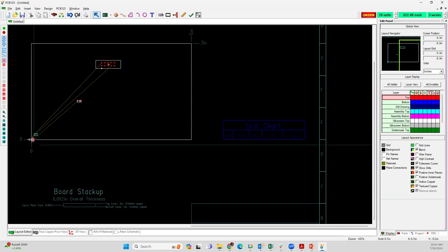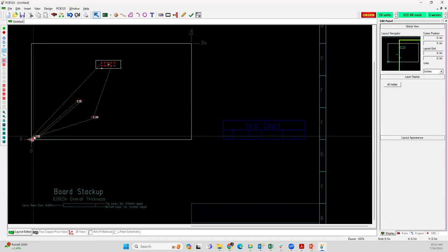So if I'm grabbing parts in the corner and I accidentally grab the board outline and change the shape of the board. So I go over to the select filter, turn everything off using the red button, and then say I just want to be able to pick components. And then all I can select is components. I no longer accidentally select the board outline.